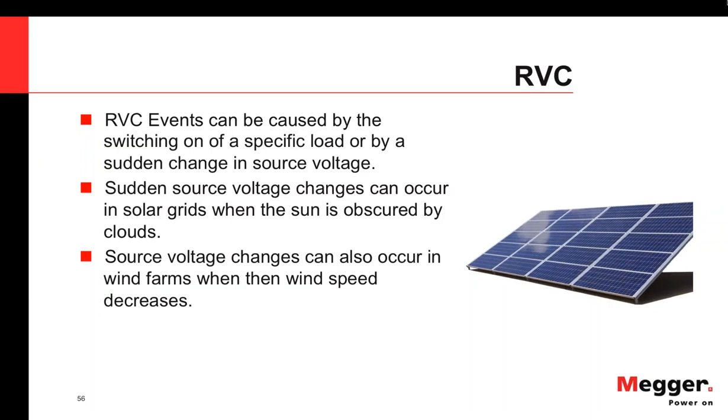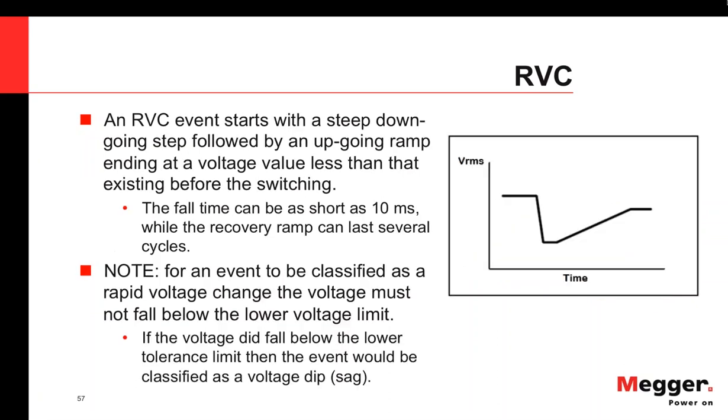And now just a reduction in voltage to 10% can result in a 34% reduction in light intensity. So a lot of this can be seen from complaints of lights flickering. And this will especially be seen where you have a potentially weak network. And again, this is typically caused by sources that change. This can also happen if you have loads that are changing very quickly, but more commonly it's going to be a source side issue.